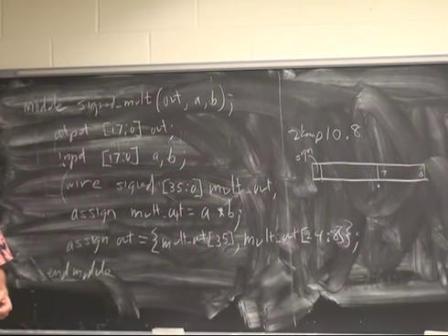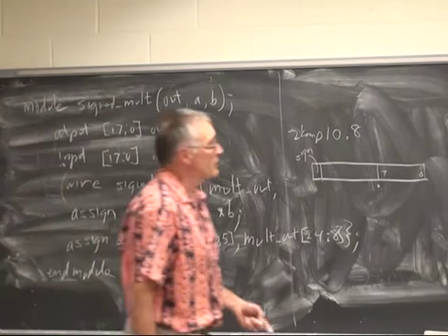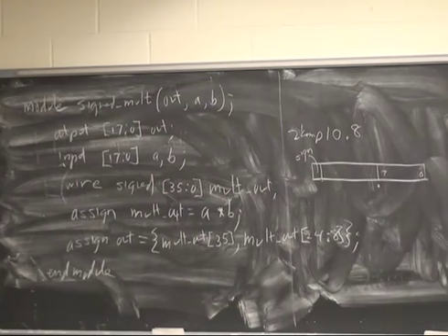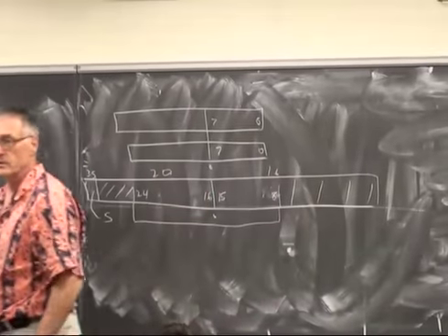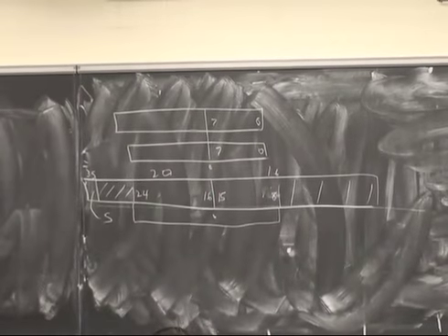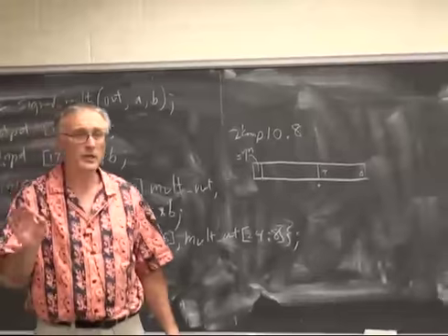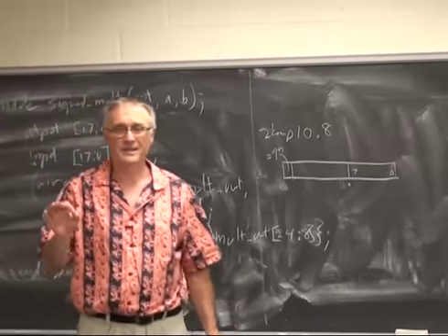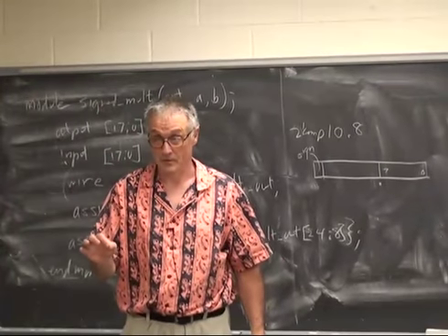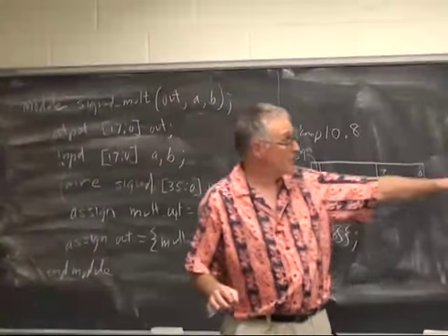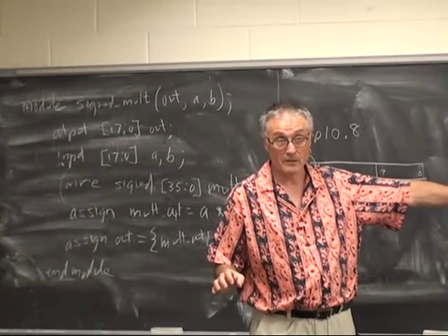Absolutely. Everything's a compromise. You're quite right. Accuracy is compromised. You're losing all of the low order digits. So accuracy is compromised. Overflow is compromised. You're losing all of the overflow digits. So for DSP, where accuracy very much matters, you want to save as many bits as you can.